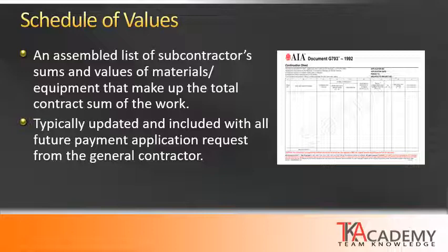This is typically updated and included with all payment applications from the general contractor, and the architect is able to review the payment application with the schedule of values to determine the type of work that has been completed and the percentage of that work that has been completed, to see if the contractor is invoicing the proper amount for payment.